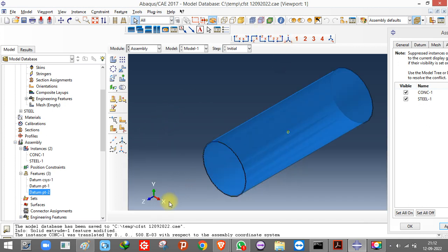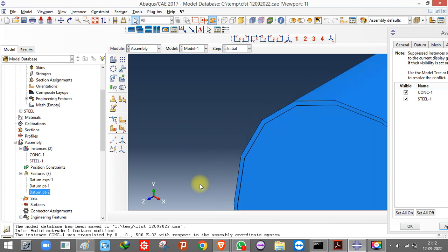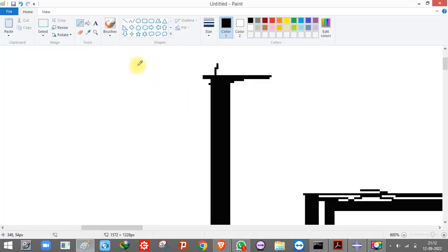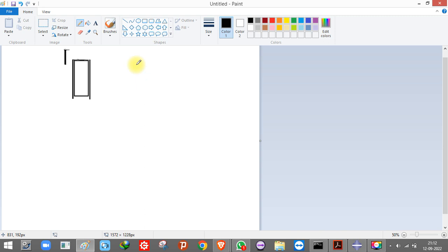So this is okay. And I found from my experience that if you do not consider this, concrete directly starts taking the load, and it gives you a failure like elephant foot failure. This is called elephant foot failure. What do you mean by elephant foot? If you have seen an elephant foot, at the bottom of the foot, due to excessive load, it bulges like this, isn't it?